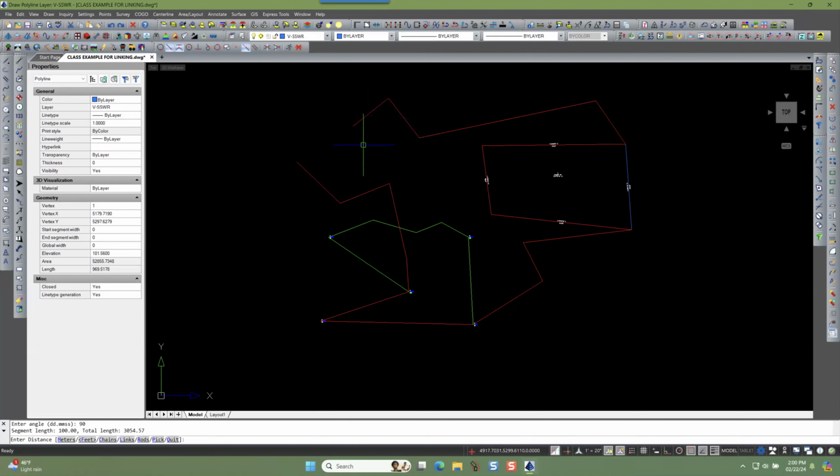There it is. Now notice it's still in distance mode. So I'm going to go another 100 feet. Okay, I'm going to choose by angle. And again, angle right. And so this time I'm sitting here, looking back here, and I want to turn an angle right of, let's say, 270. And there it is. And I can type Q to quit. So that quits me out of the distance entering method.